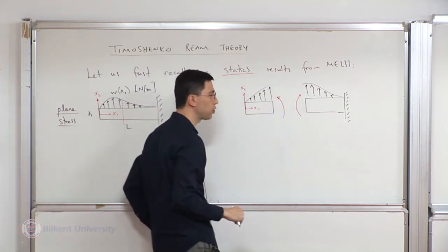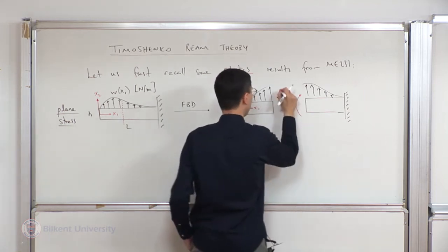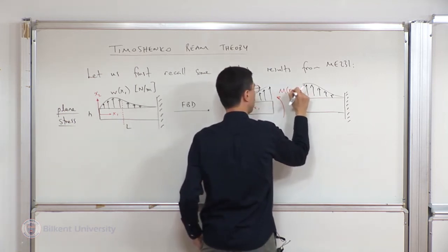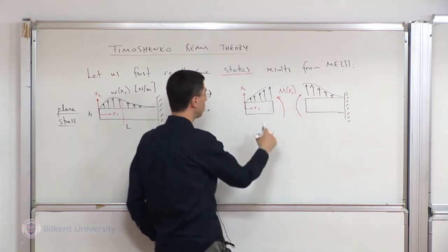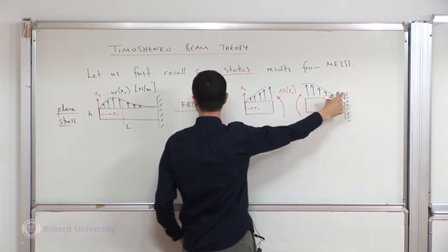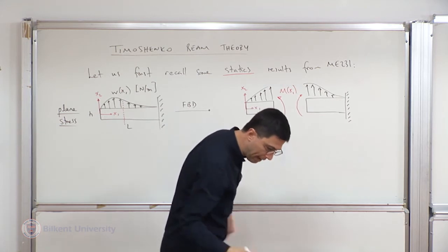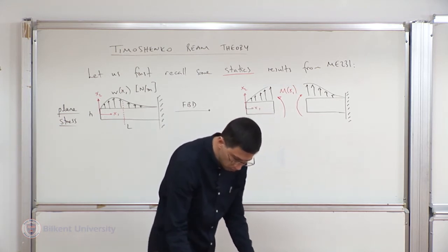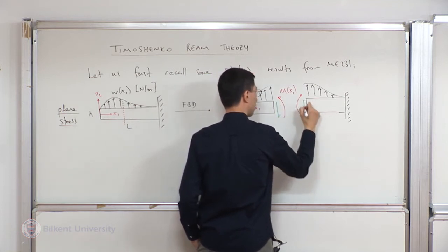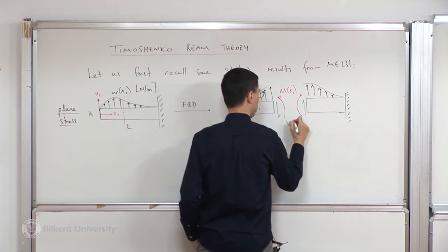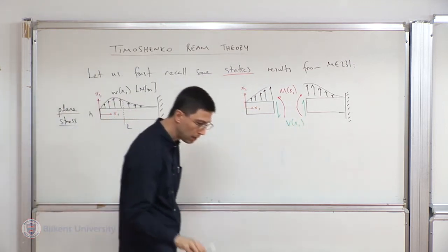So this default convention helped us communicate effectively. This is the internal bending moment default direction, positive, and it is a function of x1, of course, because it's a cross-sectional quantity. This is the default direction for the distributed load. And eventually, we have the internal shear force, the default direction being as such. We indicated that, as usual, with V.